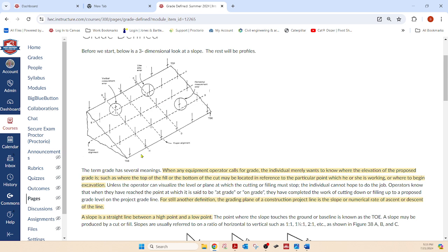It'll be a slope. Now, as he's dumping these lifts, let's call them, and making these stairs or bleachers, if you can picture that, he's going to be setting stakes on his way up. He'll set these stakes, these are toe stakes. Then when he dumps enough dirt to get up higher than where he wants his second stake, he will set the second stake. And we're still building this thing and cutting this thing because it's still bringing dirt in, going up, cutting it down, making the stairs or the steps, and so forth and so on.